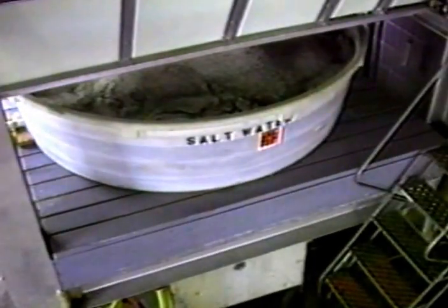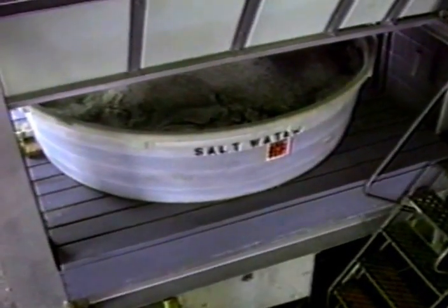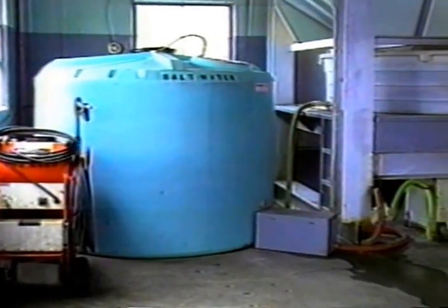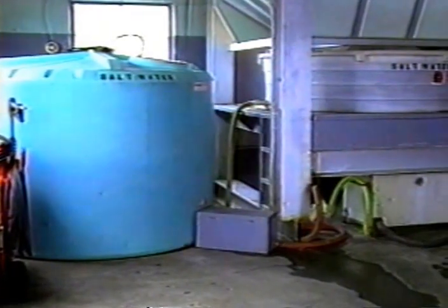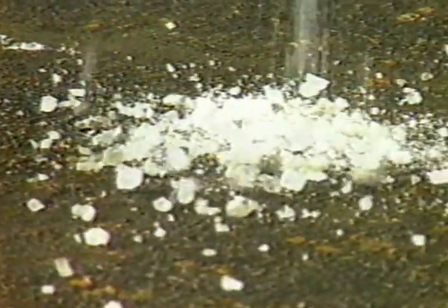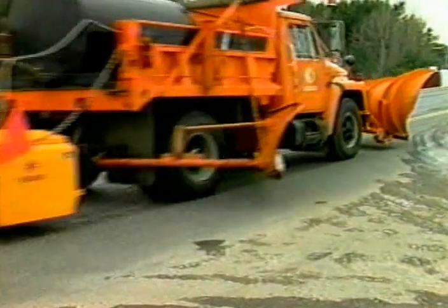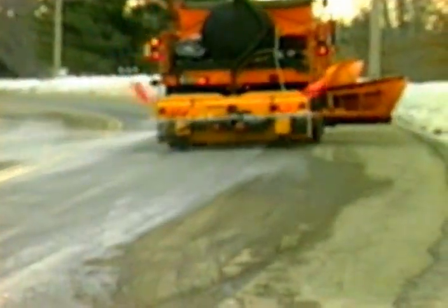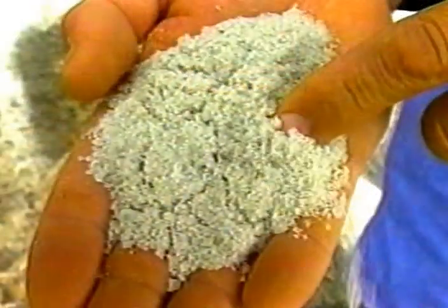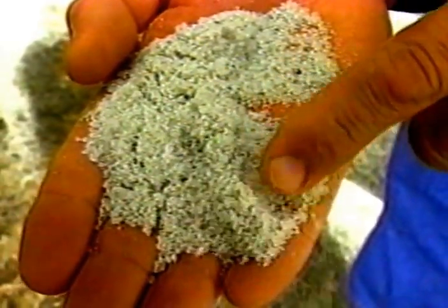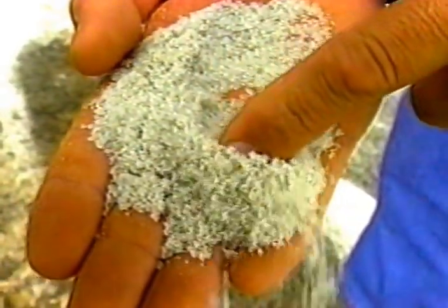For temporary or small-scale production of saturated brine, up to 600 gallons per hour, simple batch units can be built using small, commercially available sheet metal tanks. Because of its greater ability to penetrate ice or snowpack, salt used for de-icing is generally coarser than that used for anti-icing. Since anti-icing treatments are made before an ice or packed snow layer develops, penetration is not an objective. Finer salt will dissolve and coat the road surface with anti-icing solution faster, and its surface area holds more solution.